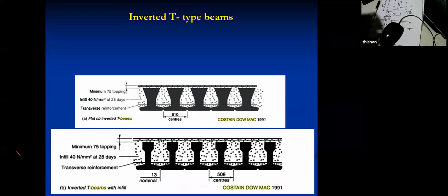So before we look at reinforced concrete bridges, we look at a little more about the evolution and construction, because if you want to design a good bridge, first you have to have a reasonable idea about the construction aspects of it. Then only can we convert all these construction notes and associated other notes to the design. Otherwise, you might do the design only for live loads, and you might find the loads that occur during construction can be as critical as the maximum forces and moments due to the live load scenario. So because of that reason, it's good to know about various construction aspects of it.